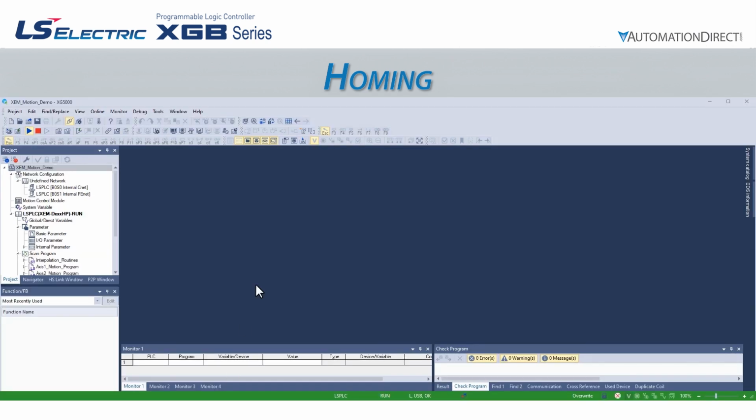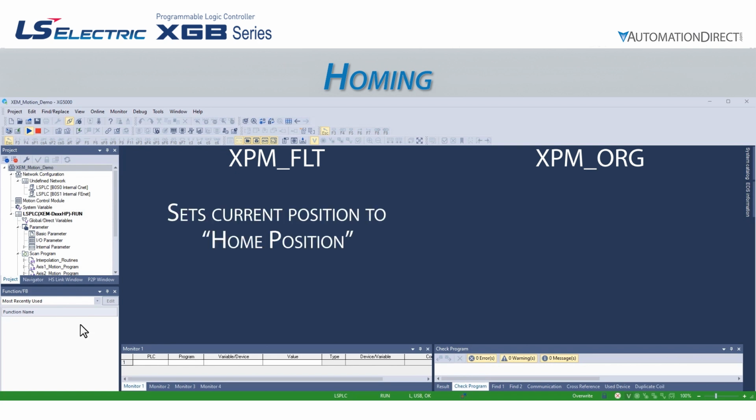Now let's look at our XG5000 project. To initiate a home function, we can use one of 2 function blocks, the XPM FLT function block or the XPM ORG function block. The XPM FLT function block simply sets the current position as the home position configured in XGPM for the axis, so no axis movement will result.